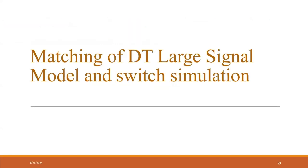Then what we do is we match this discrete time large signal model with the actual switch simulation. We have the switch simulation file which is in Simulink. We run that file, we get the data, the switch simulation plot. Then we run the discrete time model for the same conditions, for the same controller, and we get the response for the discrete time large signal model.